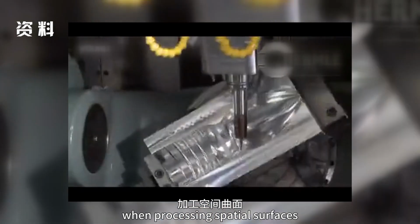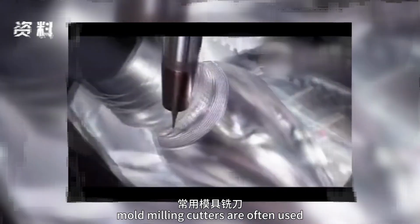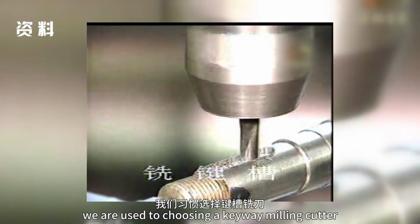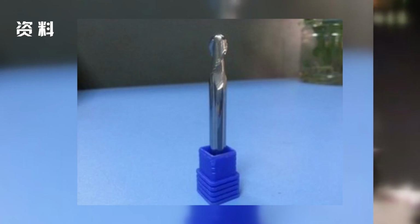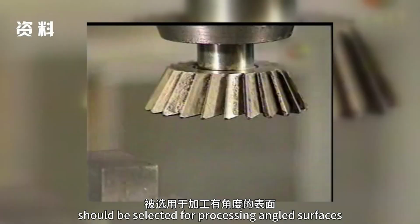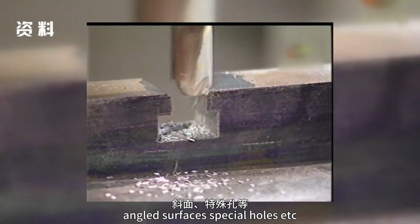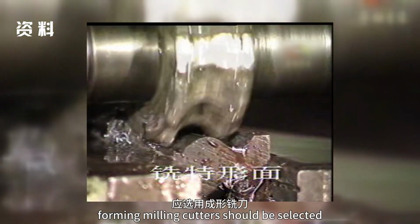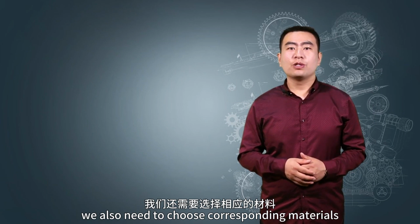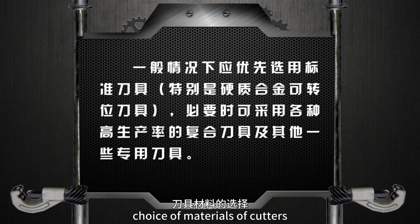When processing spatial surfaces, mold cavities, or convex mold forming surfaces, mold milling cutters are often used. And when processing closed keyways, we are used to choosing a keyway milling cutter. Drum-shaped milling cutters should be selected for processing angled surfaces, and when processing various straight or curved grooves, angled surfaces, special holes, etc., forming milling cutters should be selected. Besides the selection of types, we also need to choose corresponding materials. Choice of materials of cutters.